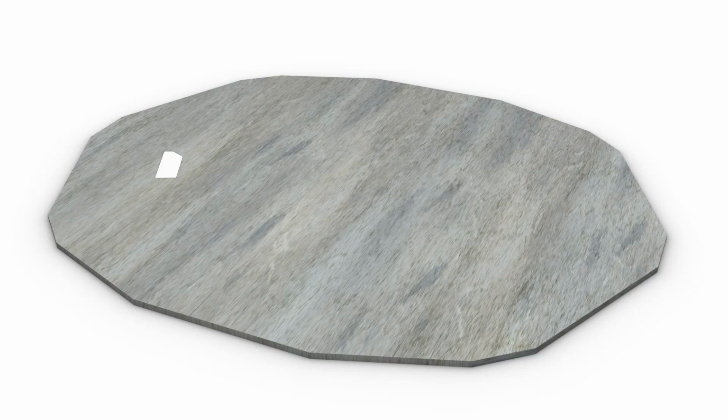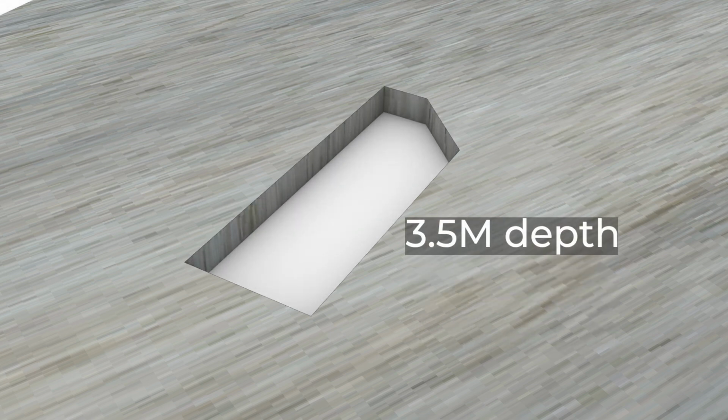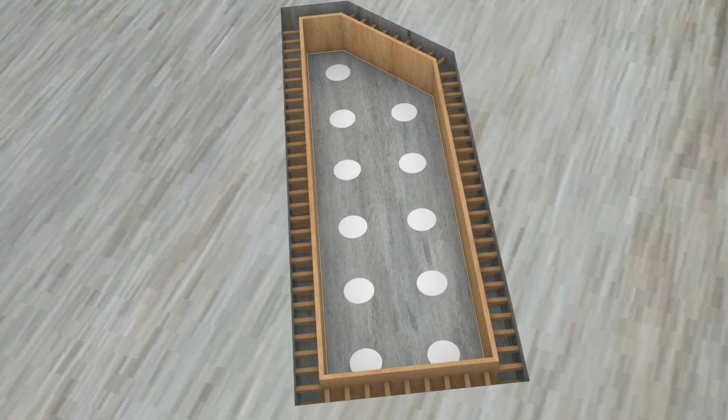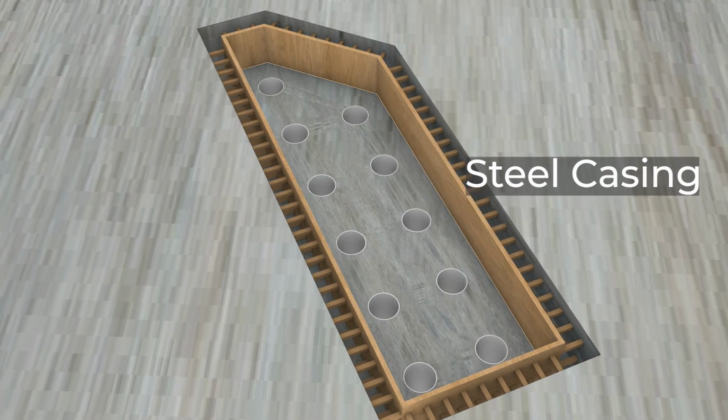The process begins by excavating the mat foundation's area to a depth of 3.5 meters, installing temporary structures to support the zone. Next, to support the weights of the mega columns, drill piles with a diameter of 2 meters and a depth of 35 meters are created. To prevent soil collapse during this process, a steel casing is inserted first.